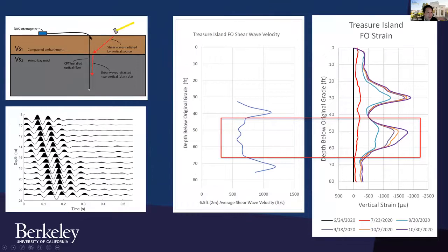At the same time, we can use this to measure vibration. That means that if you do geophysics, you can also measure and then do the Vs measurement, with a little bit of similar analysis. What you can do is derive your shear wave velocity measurements using just a cable that you already installed, and use what we call distributed acoustic sensing that measures the vibration. And that links to the soft part of the ground.